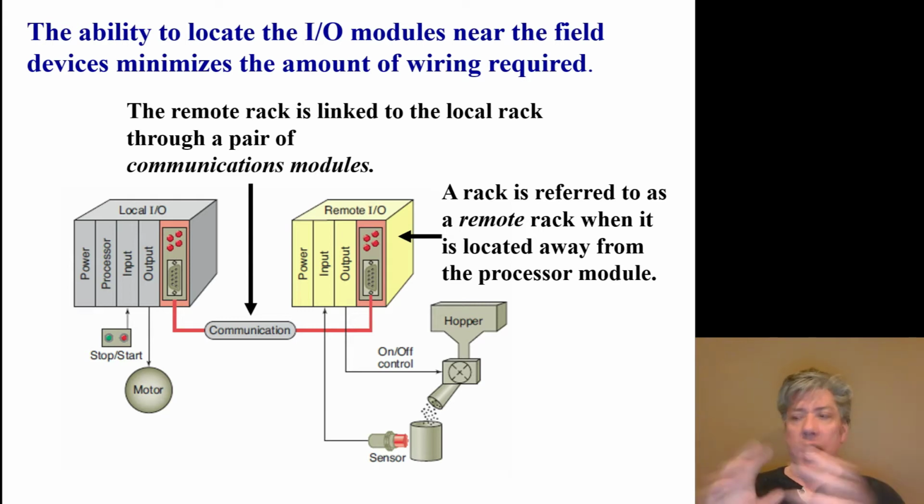of having every single wire necessary for every single switch, for example, what you have instead is a remote I/O module that has the wiring connected for all those switches, and then there's communication to send the status of all those switches back to the main PLC that's actually doing all the processing of the inputs to decide what the output should be. And of course, that remote I/O not only has input, it also potentially has output in order to drive actuators and things that are remotely located. And the whole point here is to not run so many wires.